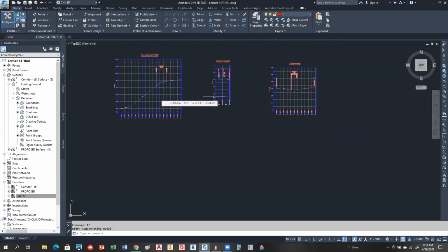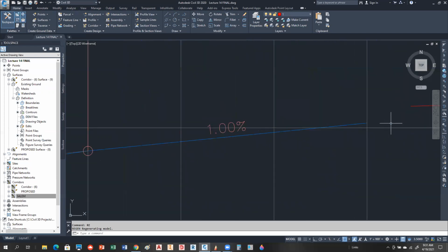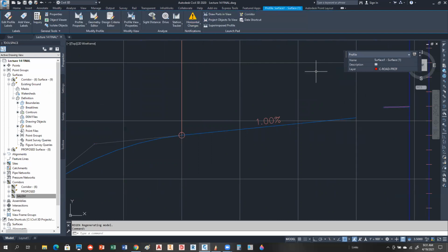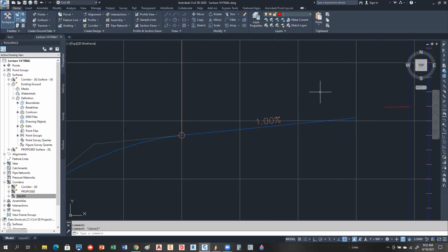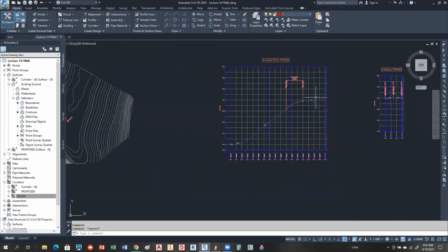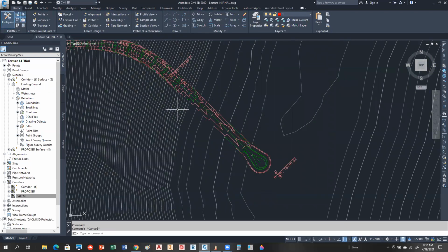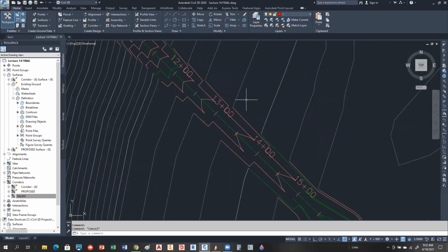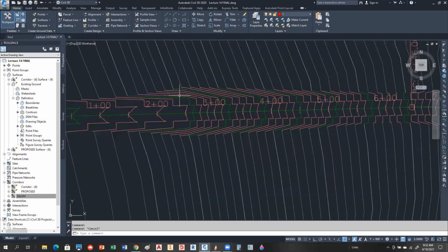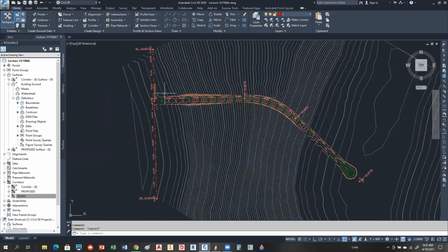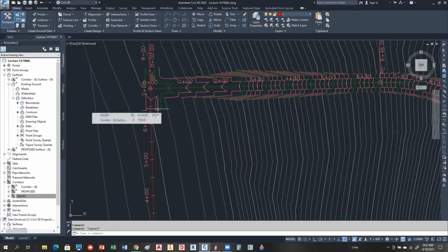And even though this layer is the layer it's supposed to be on, if you click on that, notice it says it's on that C road profile layer. Yeah. I mean, that layer's on and it's, so I don't know. It's like something gets masked out on it. Right. So there might be some kind of other masking going on. And it's possible that the corridor is masking it. I'm not sure. Or the surface. I'll try to figure that out, but I'm not worried about it too much.